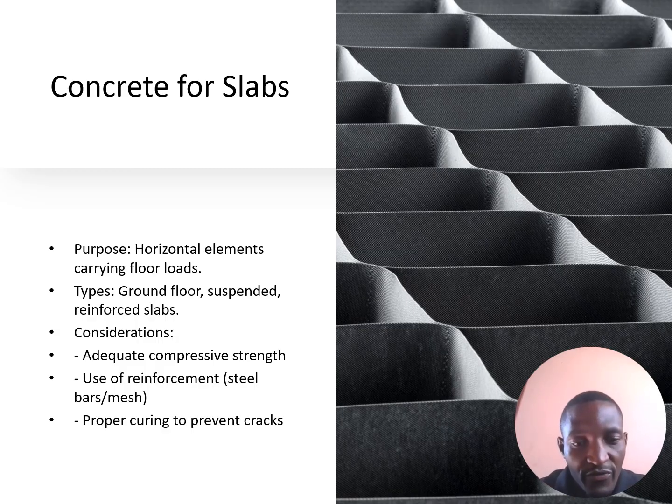And then we have things that we should take into consideration. Adequate compressive strength, use of reinforcement, steel bars or mesh. And the last one is proper curing to prevent cracks. We must make sure that our concrete goes through the process of curing so that we can avoid the cracks.